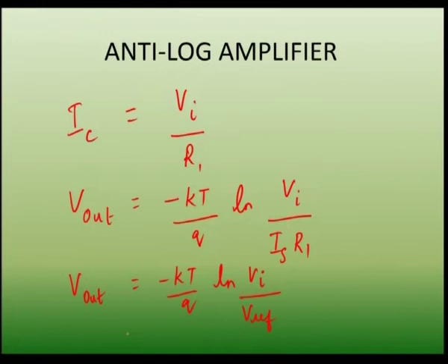So, what is the disadvantage of this log amplifier without the compensation technique? It is the temperature. If the temperature increases, then the saturation current of the transistor will also change. So, we have to compensate this parameter. So, we are going for the compensation circuit, as we are giving the V reference separately in another operational amplifier